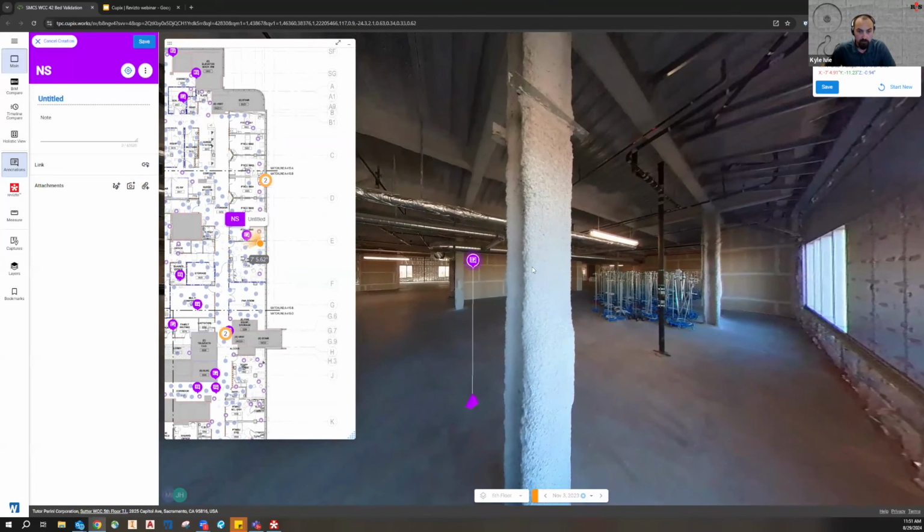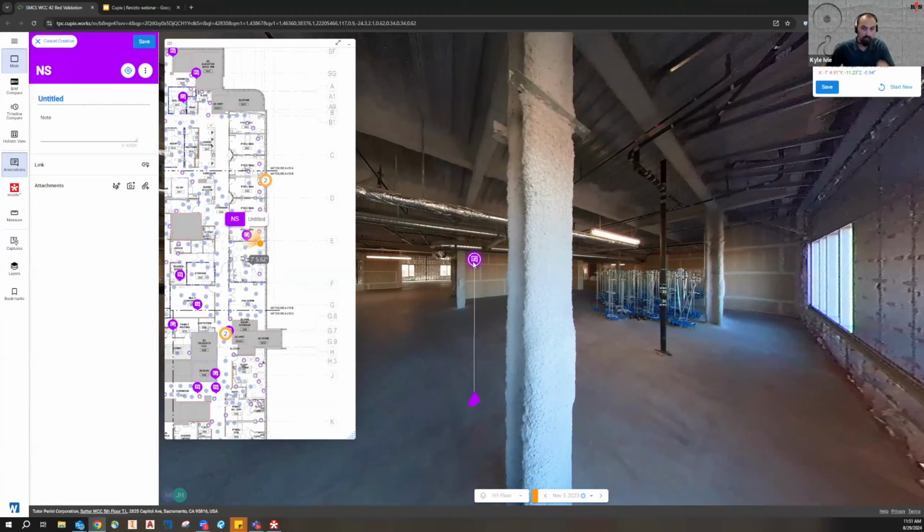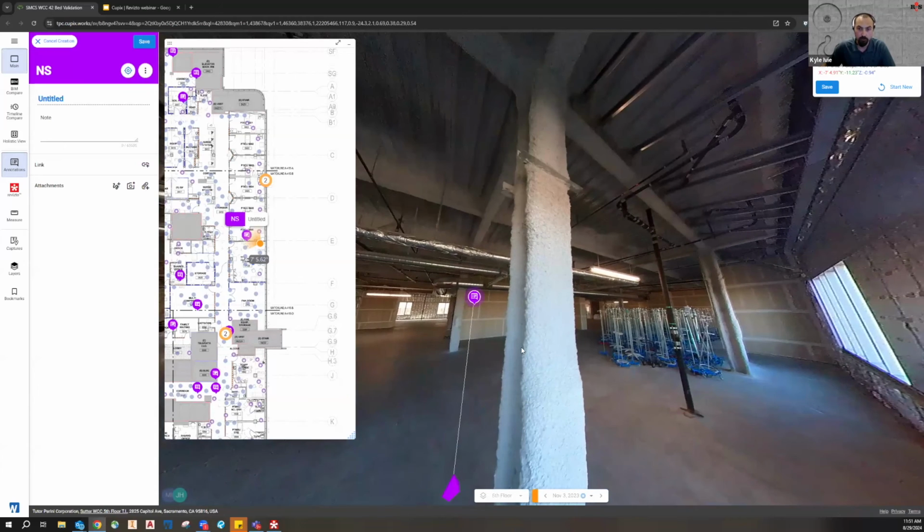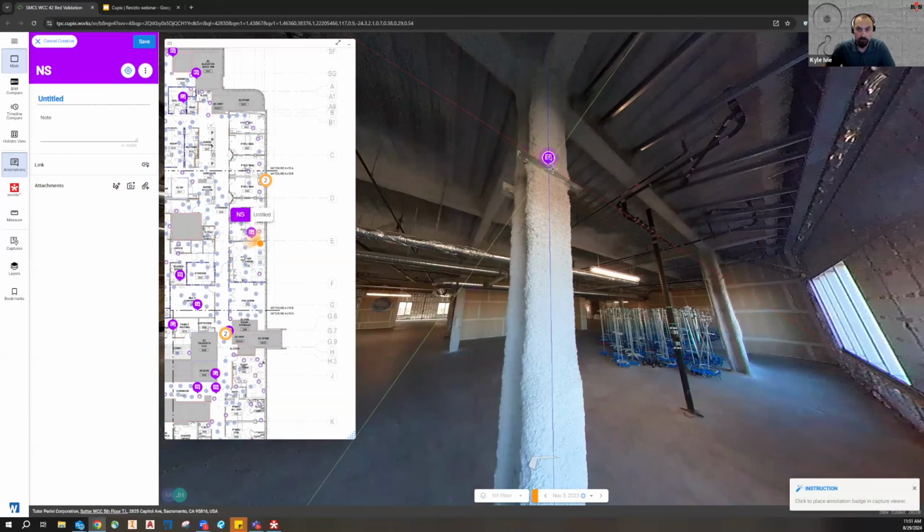When I clicked, it brought me a little bit further, and it dropped the annotation in a generic place in my near vicinity. So if I didn't like the position of that, for instance, if I would really like the annotation to be there at the location of the issue, I can quickly select this target button, reposition annotation, and then it allows me to use the XYZ to drop that annotation to a better place. After it recognizes its coordinates, it'll drop it there.